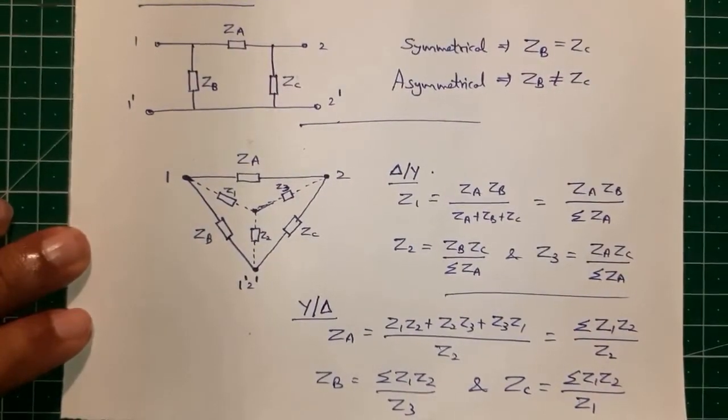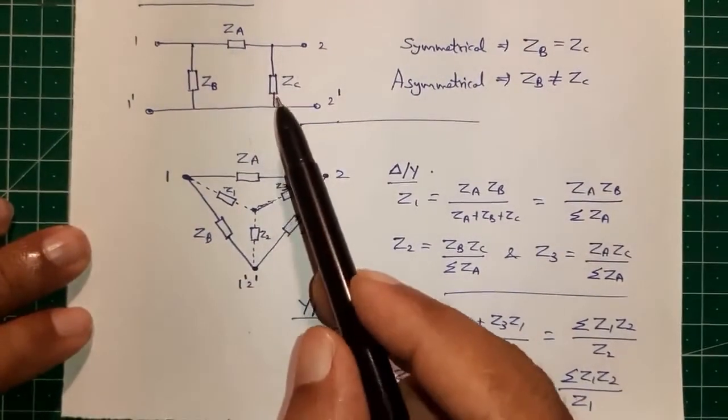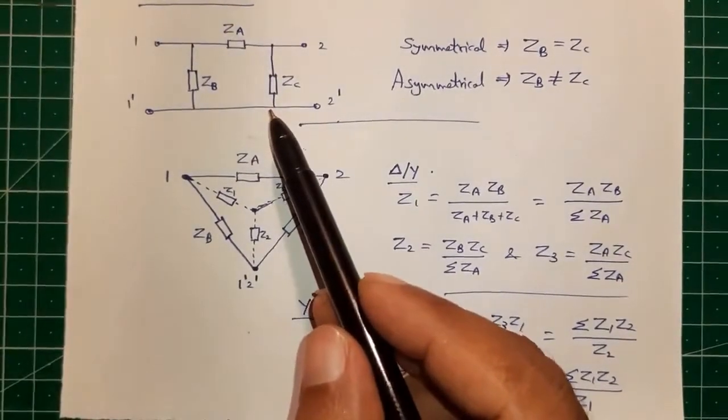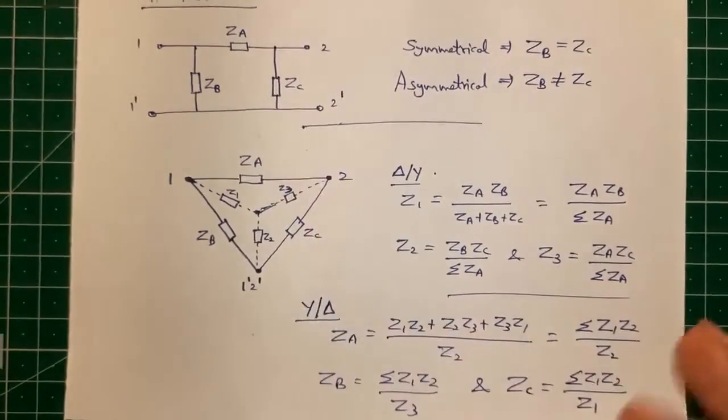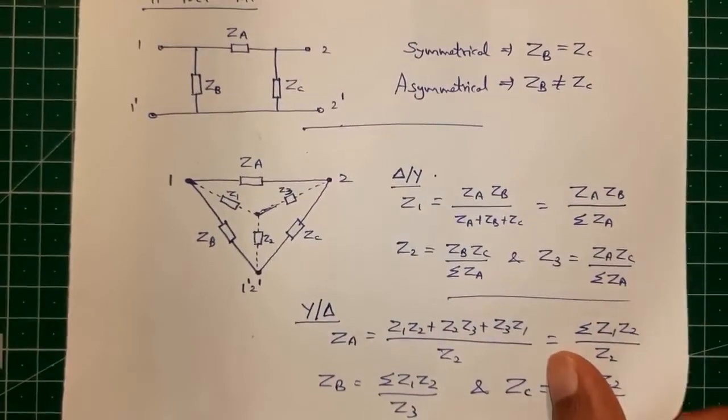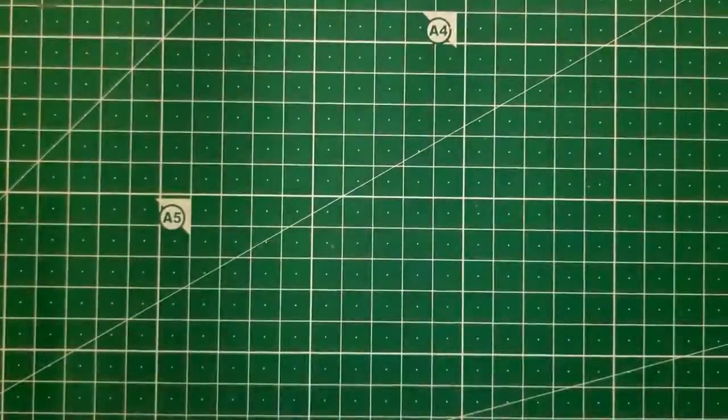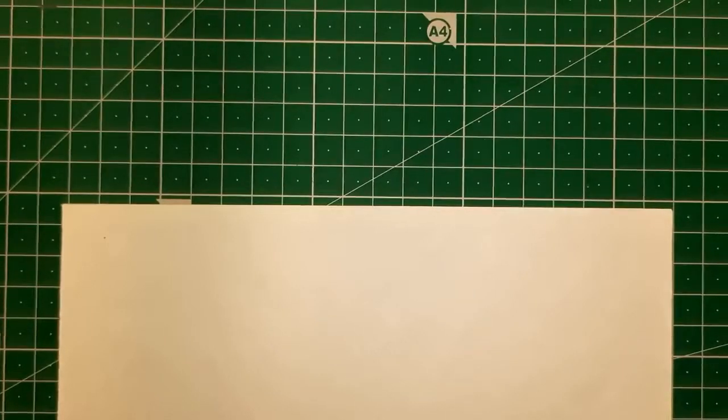So we have to approximate short and medium transmission lines in terms of T and pi networks for easy analysis. So we have seen the first two network configurations, the T and pi networks, which can be used for representation of transmission lines for analysis purposes.